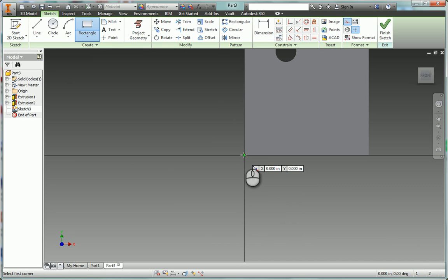And I can come down this corner, come up here to locate the center. And the one going across there is D11. So I'm going to call that D11 equals, what is the hole depth location? 2/3 of the overall plate. So that'd be D0 times 2/3. And good.